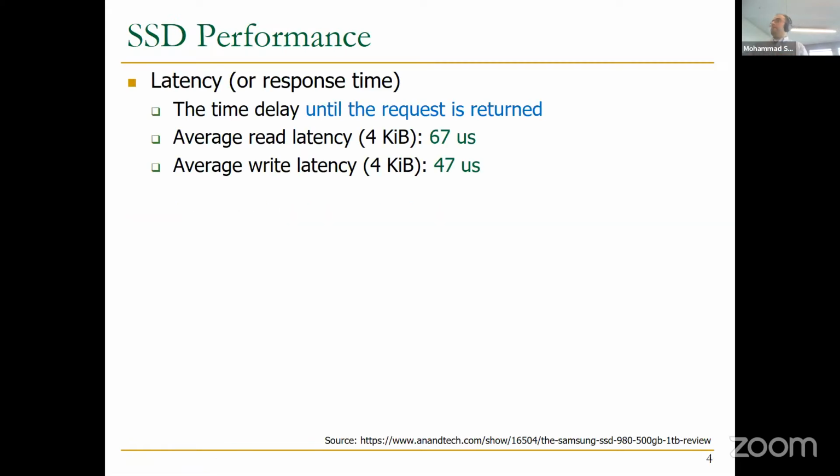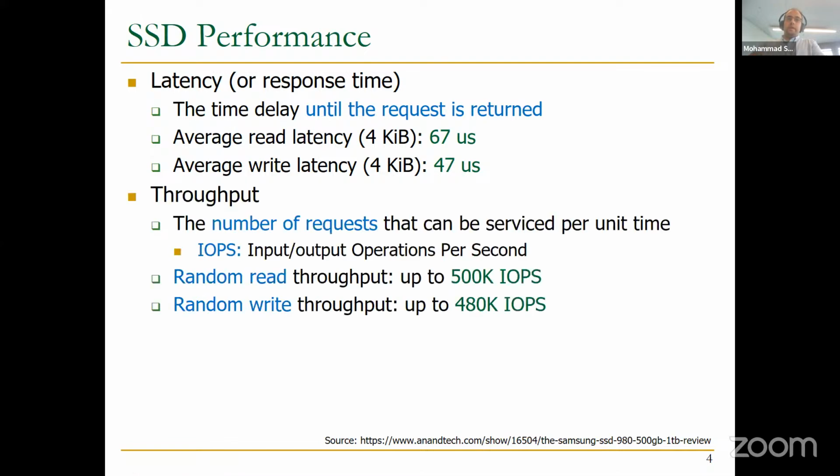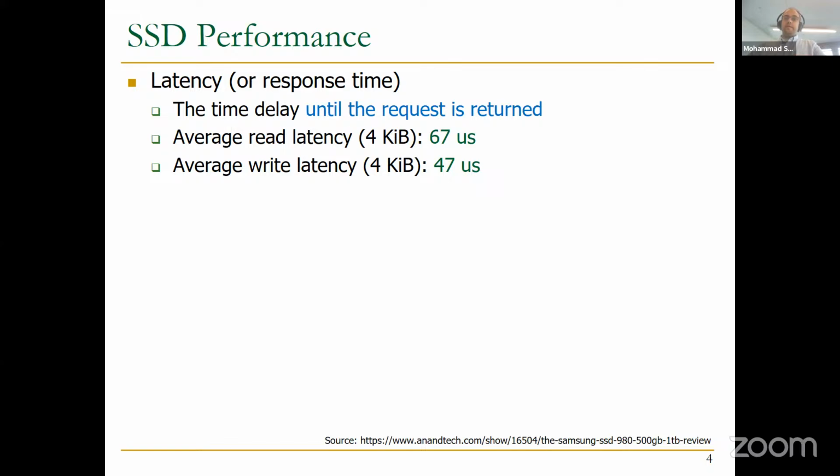Okay, so yeah, let's analyze the SSD performance a little bit. Basically, latency or response time is the time delay until the request is returned to the processor. And we know that the average read latency for a page, like a 4 kilobyte page, is around 67 microseconds. These numbers come from a data sheet, and you can see the source at this link. Also the average write latency for a page is around 47 microseconds. So you can see that write is faster than read.